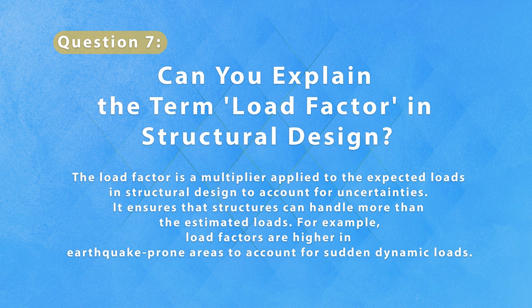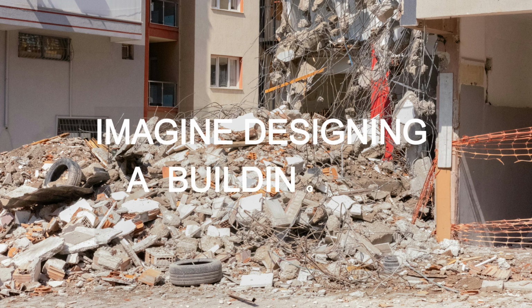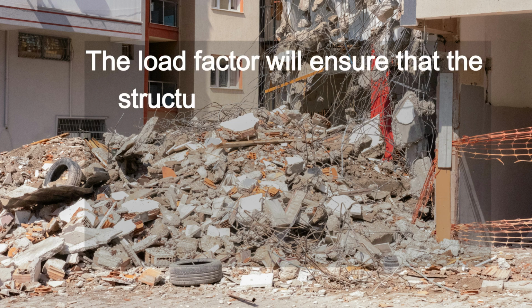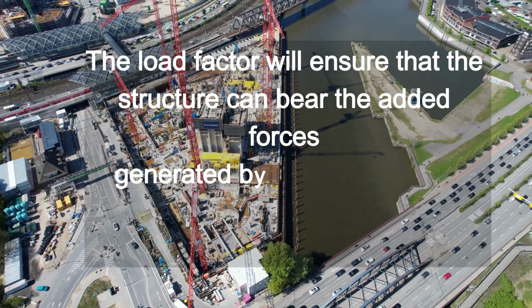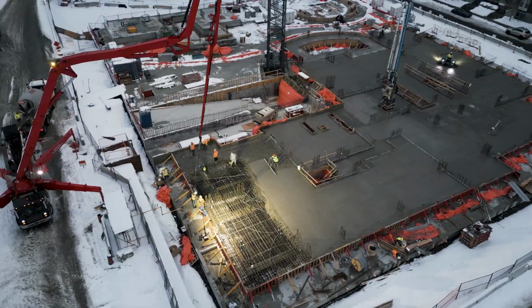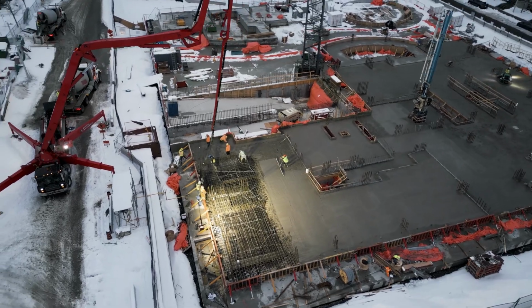The load factor is a multiplier applied to the expected loads in structural design to account for uncertainties. It ensures that structures can handle more than the estimated loads. For example, load factors are higher in earthquake-prone areas to account for sudden dynamic loads. Imagine designing a building in a region prone to earthquakes. The load factor will ensure that the structure can bear the added forces generated by seismic activity, keeping it safe even under extreme conditions. Now, let's dig deeper into concrete again.